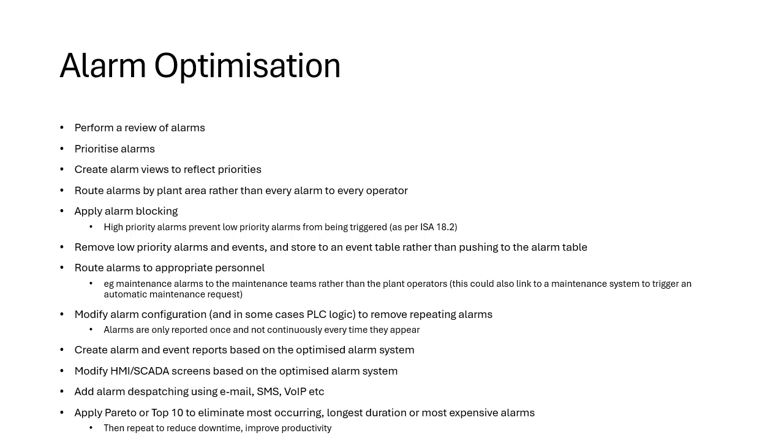As soon as something goes into the alarm state, then you would change the colour, and then they would see a box that they need to take action on. So maybe it's something goes orange or red, like I explained the colour codes earlier. But when they've got just a grey screen, they can glance at that and say, nope, nothing to worry about.